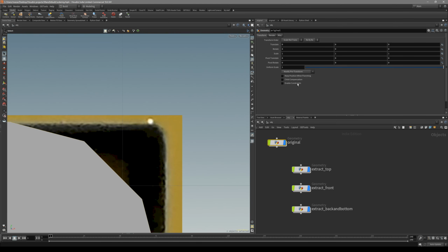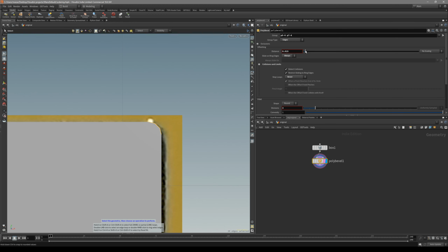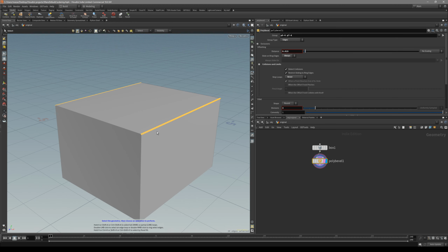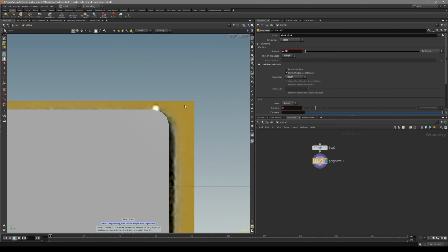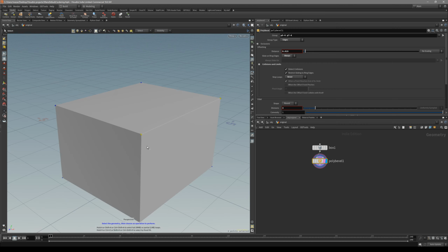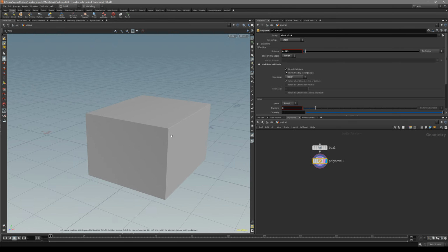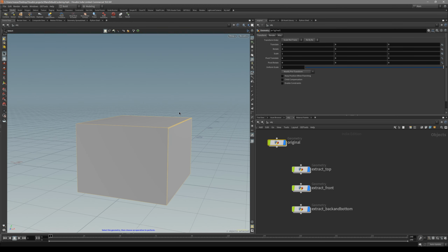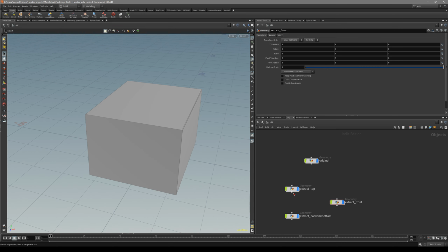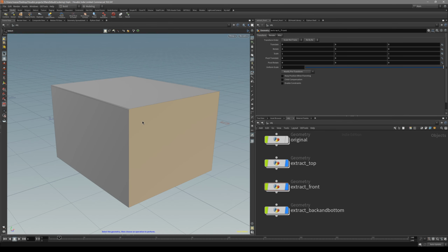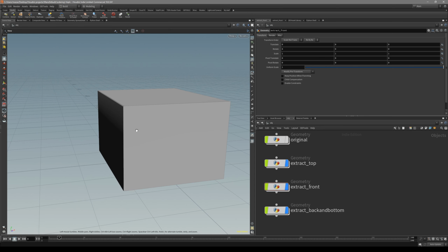So this is kind of more of a procedural way to work with. In this case, we probably wouldn't really need it because the bevel is kind of set in stone. We don't really need to change it all that much since we are basically modeling this object. But if, let's say, we want to be so sure, it's nice to have an option that we can always change this beveling. To align these nodes, what you can do is select all the nodes with Ctrl A or drag it out, and by holding down A, you can just select the very top geometry node and drag down. Now that we have set up our pieces, let's start working on them individually.